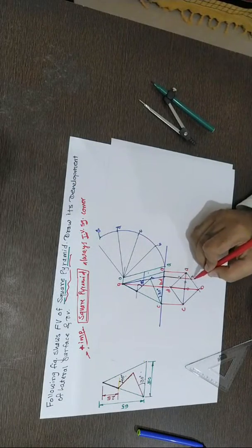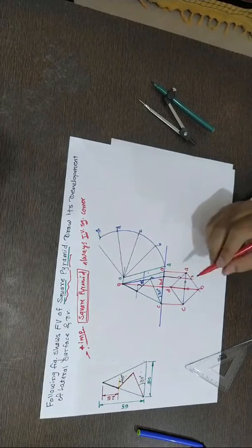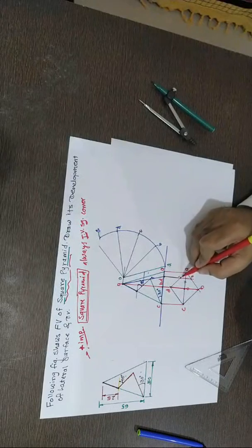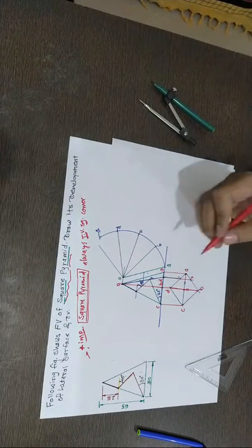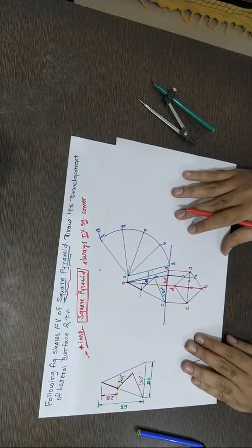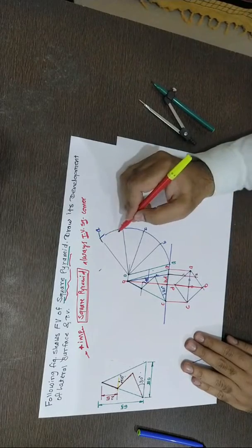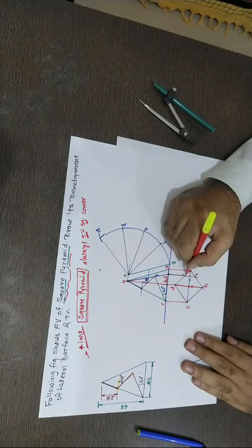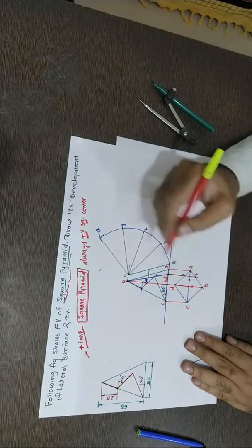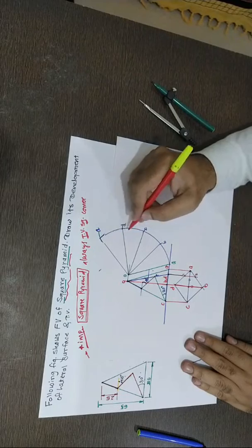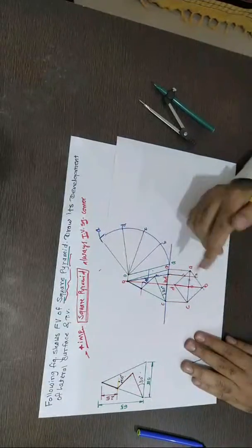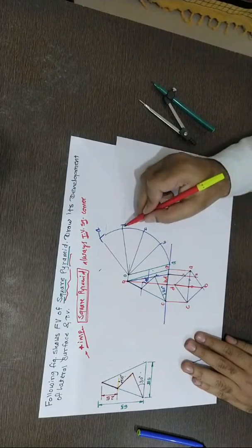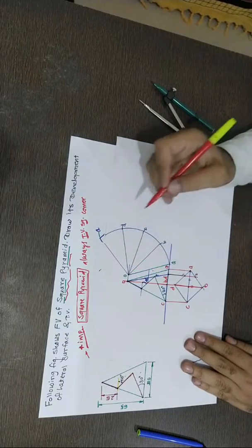This point is projected in the top view; the base edge it will cut is 1. You take the distance 1 to A in the compass, or D to 1, and mark it here on AD. So this is point number, let's say base reference point 1, between A and D. Either you can take A1 and mark from A, or you can take D1 and mark from D. You will get that one more edge.